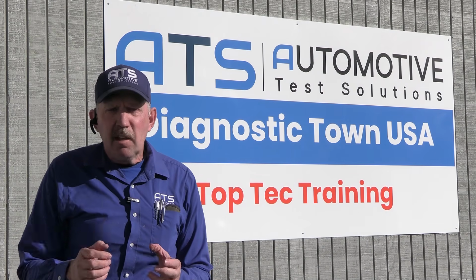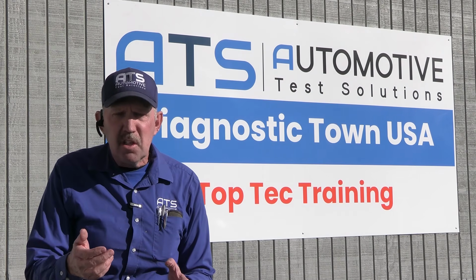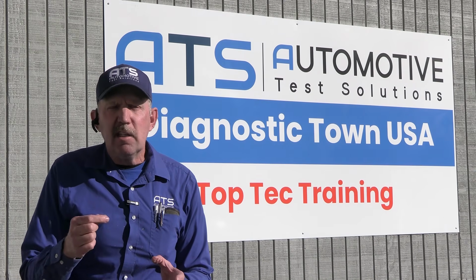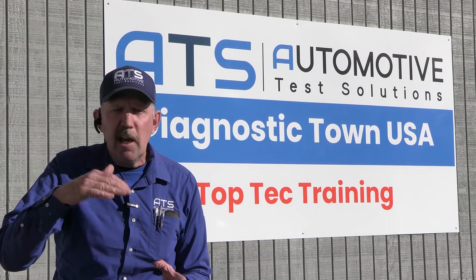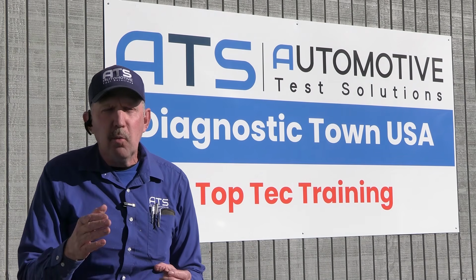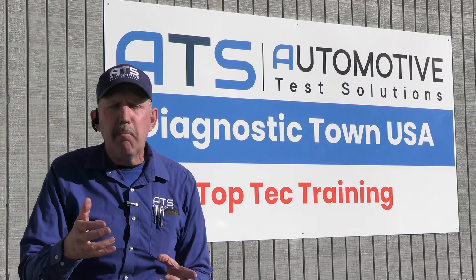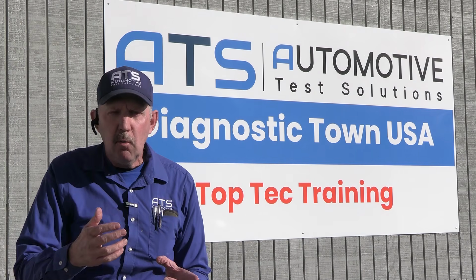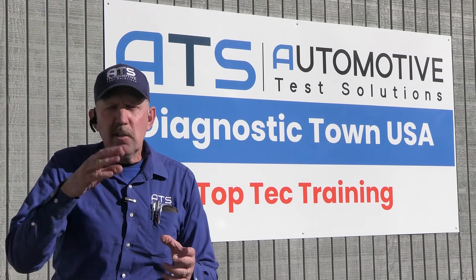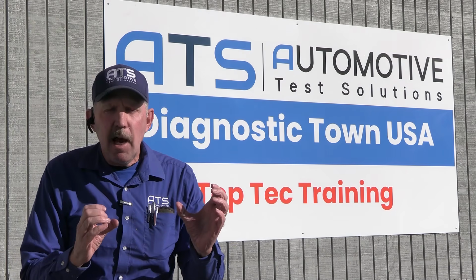But I'll tell you something that the guy who owns the shop told me. He said, yeah, Bernie, you know, I doubted your diagnosis at the time, so I took a bore scope and I went down and I looked at it, and he said I could see where the guides were all chewed up from the chain moving around. He said, so we pulled the front cover off, and then he said, I saw the real problem. One of the guides was totally chewed up and the other guide was chewed up and it broke and it was totally off. Wasn't holding the chain at all. So now the chain's just whipping around. So once the chain's whipping around, the crankshaft and the pump shaft can't be timed together.